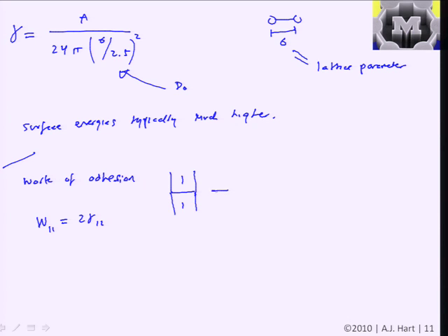So basically to do what I said a moment ago, to take, say, two halves of material, or one piece of a solid material, and decide where you want an interface and break it and separate it into two pieces. And in terms of notation, we'll say that the work of adhesion is equal to twice the surface energy gamma. Essentially, you need to apply this amount of energy to separate a surface into two unit areas.